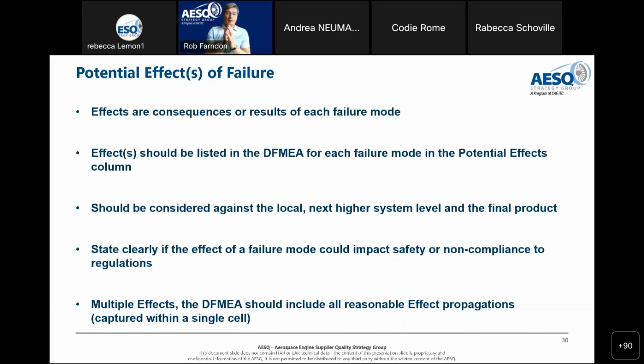so that you can understand the consequences of any failure mode propagation that you have, which, as we were discussing yesterday, implies that you need some information across company boundaries in some cases, where a design make supplier might be doing a DFMEA and needs to understand something about the system architecture and the way it behaves. It's not possible in many cases to do a component DFMEA without that sort of knowledge.